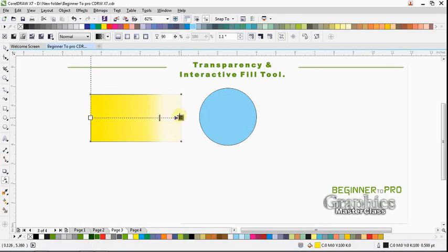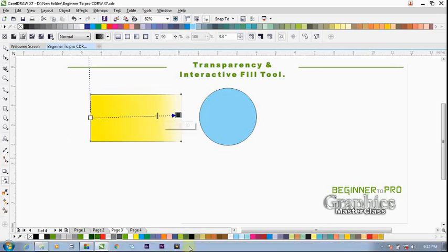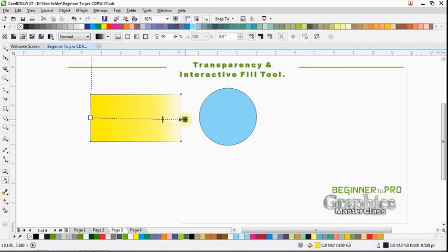One other thing I would like to show you is how you can make both sides of the object transparent. I'm going to take this back to 100% transparency. So let's say I want to make this side transparent and also this side transparent. I can change this to 100% transparency. Now you say, whoa, you changed it to 100% transparency and I don't see anything anymore. I wanted just the sides to be transparent. So what do you do right now?